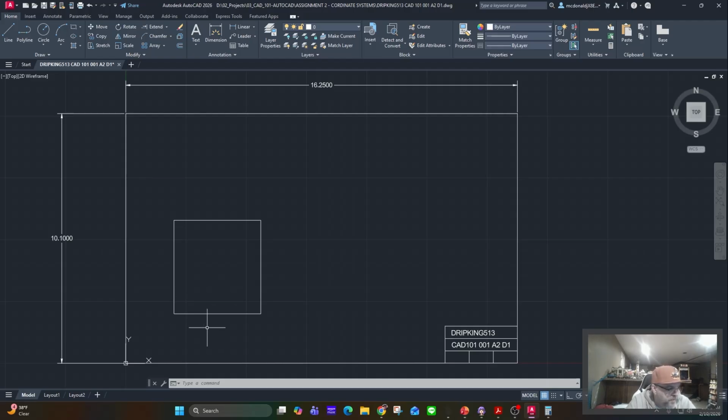So first we're going to go ahead and chamfer this corner. Right here in modify, it'll either say chamfer or fillet or even blend curves. Hit the arrow, make sure it's on chamfer. Check our command line. Chamfer, select first line or undo polyline distance or angle. Based off our sketch, we've got an angle of 45 degrees, so we're going to hit the angle. It's saying specify chamfer length on the first line. There's a number in brackets.